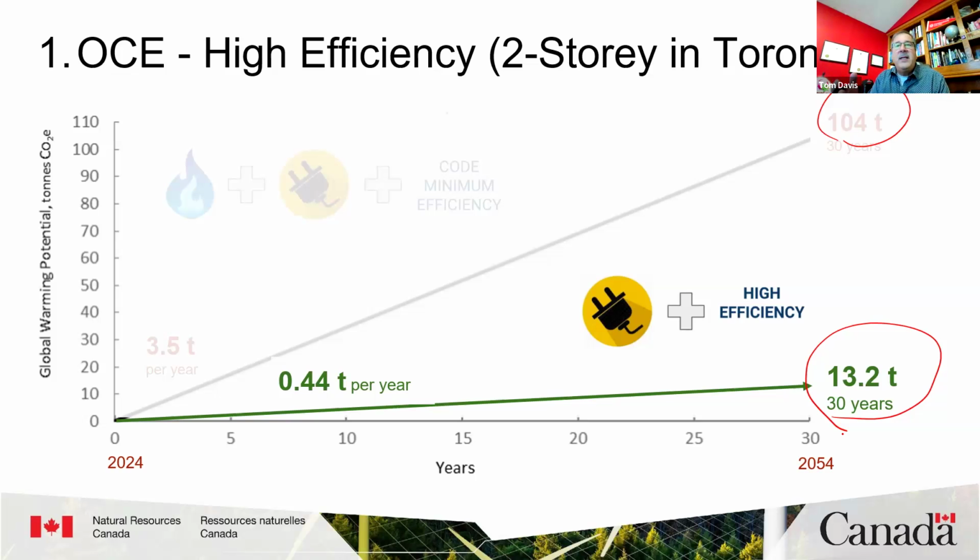So what we want to do is make our building energy efficient before we size the mechanical equipment. So we do energy efficiency upgrades, and we can determine which ones using HOT 2000. It could be just windows, it could be exterior cladding, exterior continuous insulation are examples of retrofits that I've done here in London, Ontario to achieve 20% or 70% energy reduction. The nice thing, if you can remove 70% of the demand from your home, the remaining 30% of the energy that is required can be very easily made up with solar photovoltaics or a net zero construction.